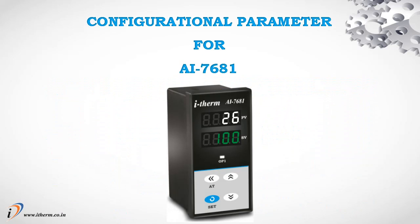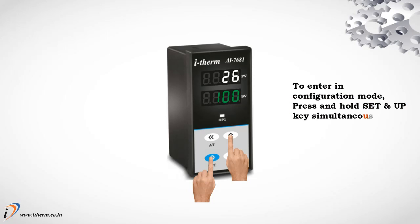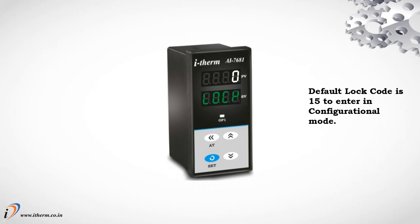Configurational parameter for AI7681. To enter in configuration mode, press and hold set and up key simultaneously for 3 seconds. After that, lock code will appear. Default lock code is 15 to enter in configurational mode.